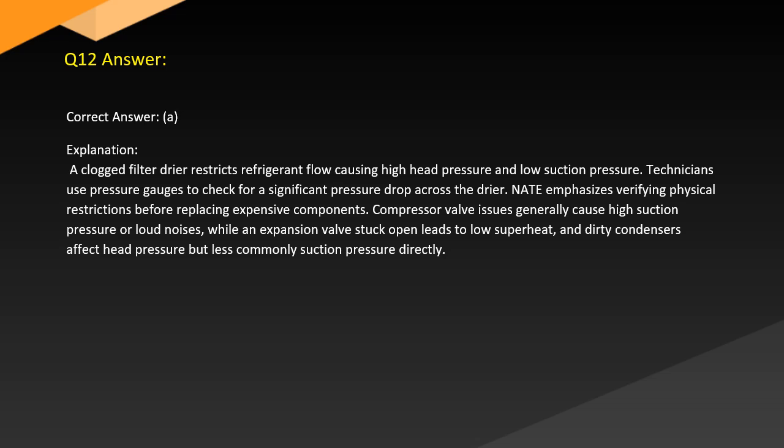Compressor valve issues generally cause high suction pressure or loud noises, while an expansion valve stuck open leads to low superheat and more. Condensers affect head pressure but less commonly suction pressure directly.